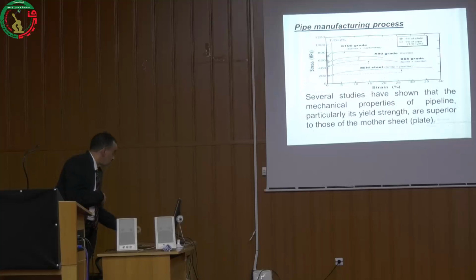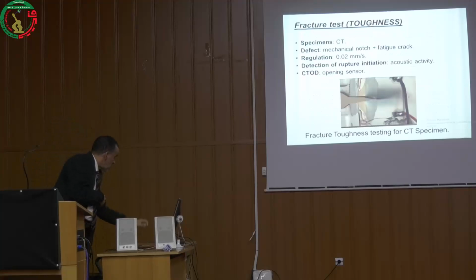For this reason, several studies have shown that the mechanical properties of the tubular structure are higher than the mother sheet or plate. Here we are answering the second question. So we used a CT specimen, and the defect was made by mechanical notch, followed by fatigue crack.